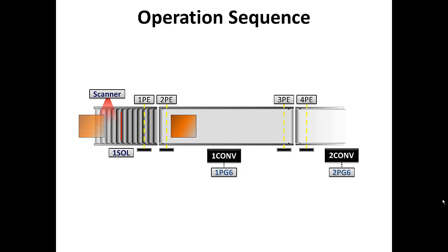Next carton comes along, code's good, it drops the stop, comes down and rests against the belt, the belt turns on and pulls it on, and stops as soon as that second carton has cleared the photo eye at the entrance of the buffer conveyor. Now keep in mind the spacing between these cartons is a function of several things. The first one is the speed of the buffer conveyor.